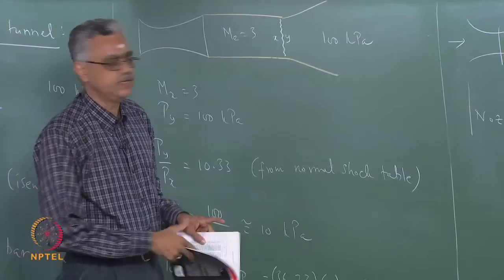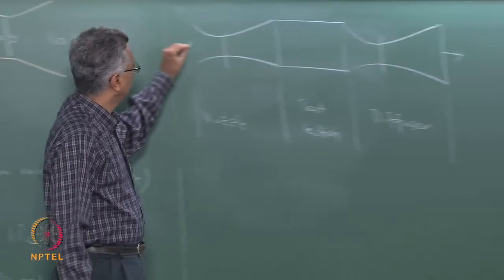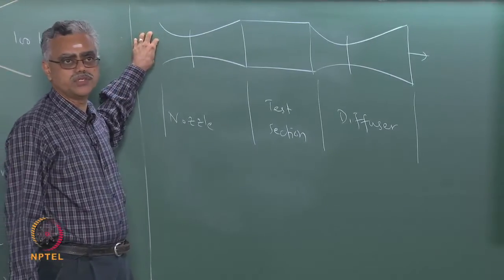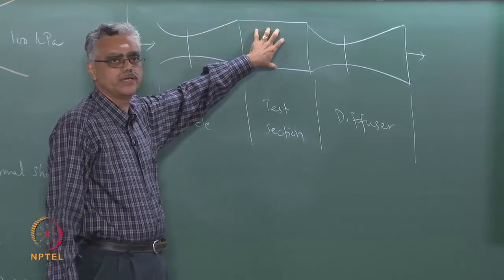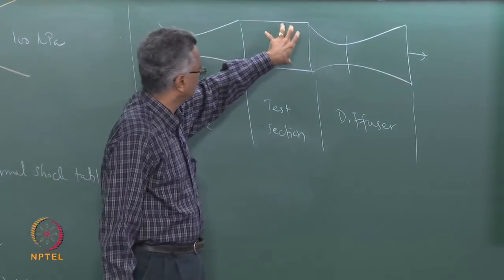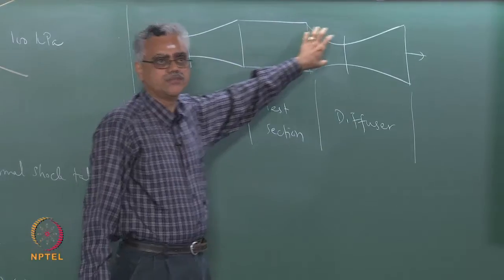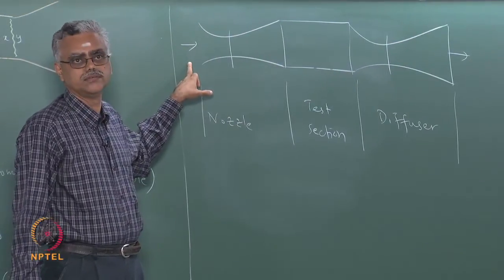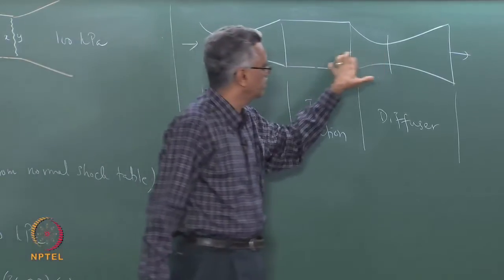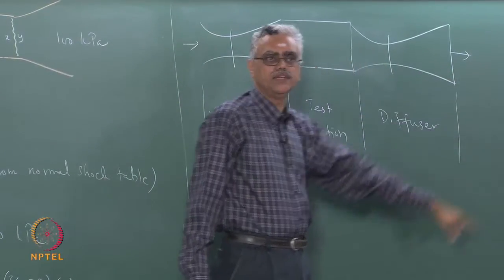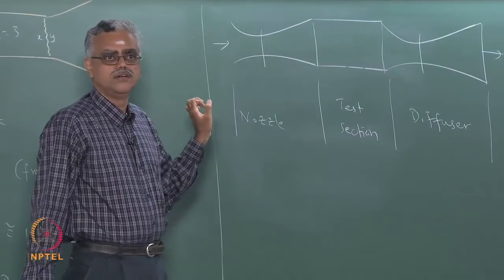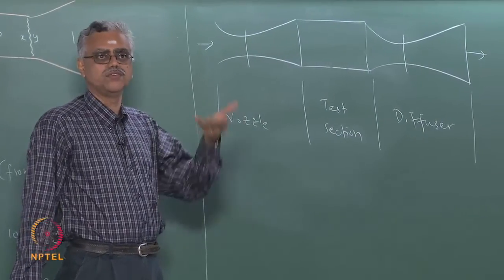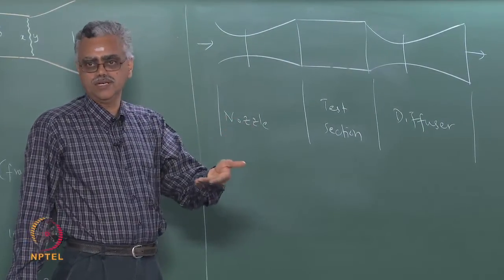The idea is during operation the air comes in at a certain static pressure, goes through, becomes supersonic, and then if I am able to recover the momentum of the air and convert that to static pressure, I can feed this air back into the inlet here. Or I am sorry, if I recover this as the momentum, I can feed the air back into my storage tank, because I have now converted the momentum into high static pressure.